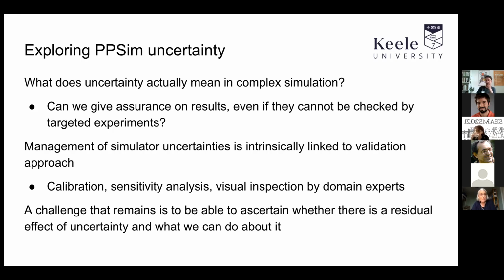So typical approaches to validation for making sure that your complex simulation sufficiently mimics the real behaviours or the observed behaviours of the reality would include calibration, which is repeatedly running the simulator with different parameter values from known ranges of parameters, for instance, until you get behavior that looks like the original behavior of the system that you're simulating.